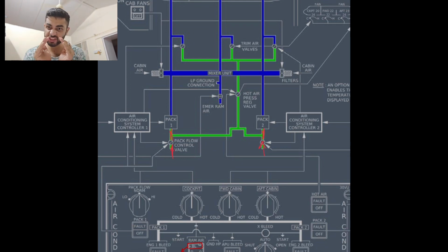So it has to be a very small, very thick pipe, because it's very high pressure air being provided. So this small pipe is attached, and it's much smaller compared to the low pressure pipes. The low pressure pipes are the massive, big yellow pipes you usually see coming near the nose area of the aircraft. Those are low pressure, but here we use high pressure because the packs usually receive air bleed from the engine itself.